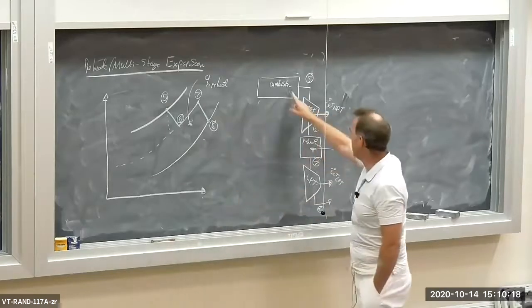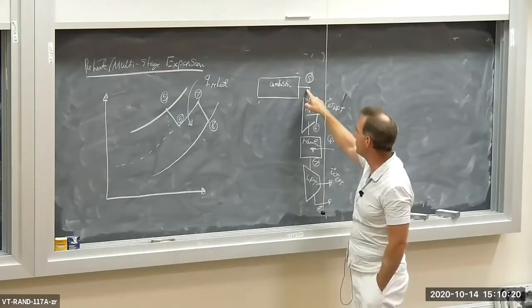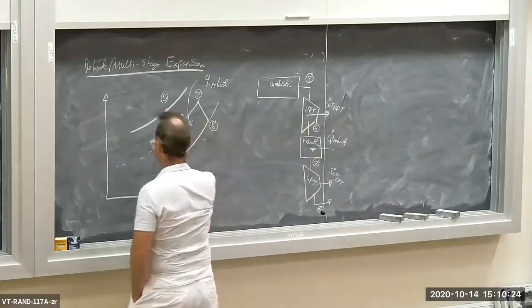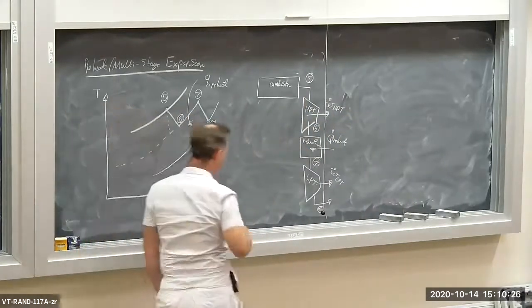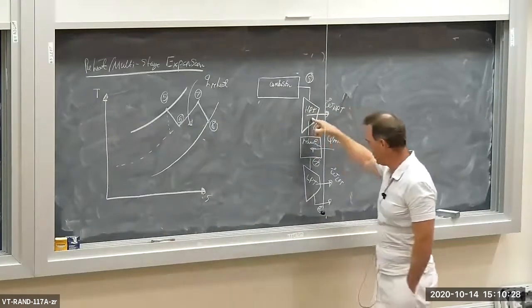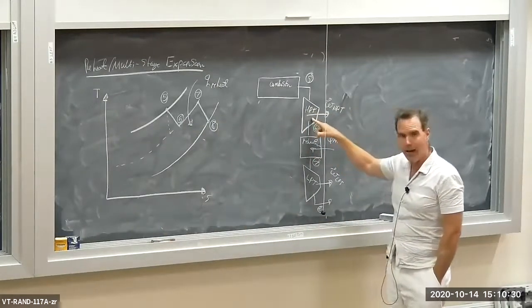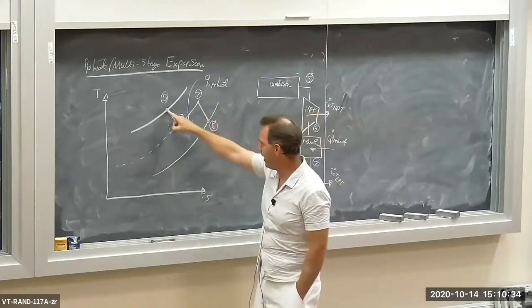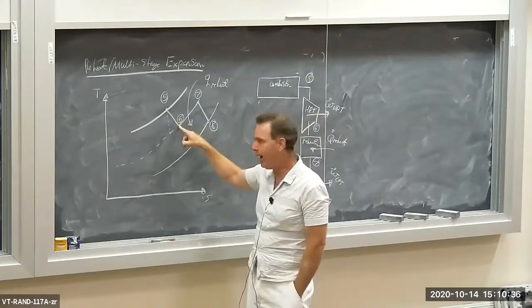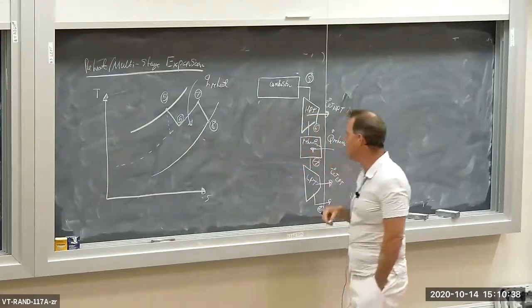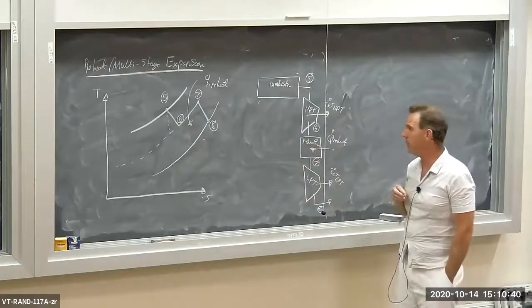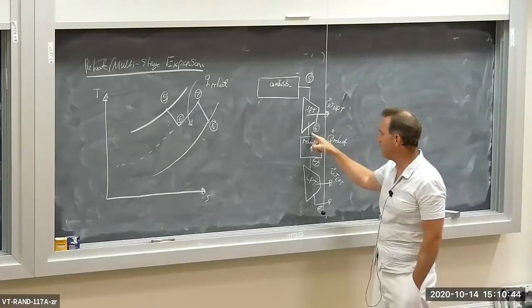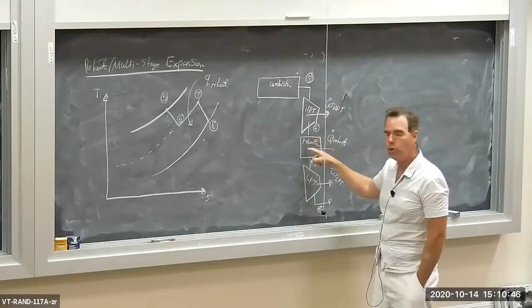So here we have the combustor, and the outlet state for the combustor is state 5. So instead of having a single expansion in one turbine, we expand it through a high pressure turbine, so 5 to 6 is expansion in a high pressure turbine. Notice that these are irreversible devices here. Then, once we get to the outlet of the high pressure turbine, we reheat.